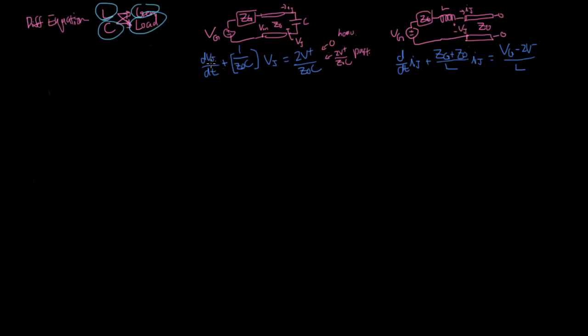So the homogeneous solution gives you something that will always give you 0 going in, which is kind of the source-free solution. So if there isn't a voltage at the source, then the homogeneous solution would be your overall solution, and the particular solution would just be 0. And then if there is a source, in this case there's a voltage source going on, you have an equation that when you run it through this will produce this right-hand side as the output. So let's start by looking at the homogeneous solution, and that is what our step 3 is. So step 3 is